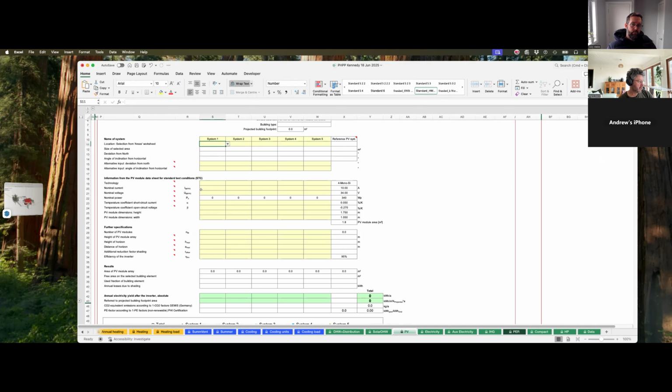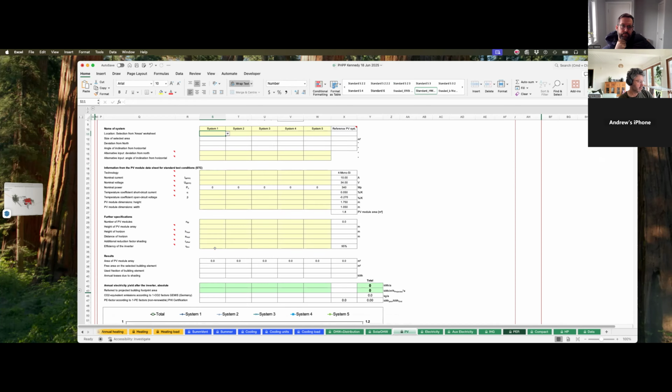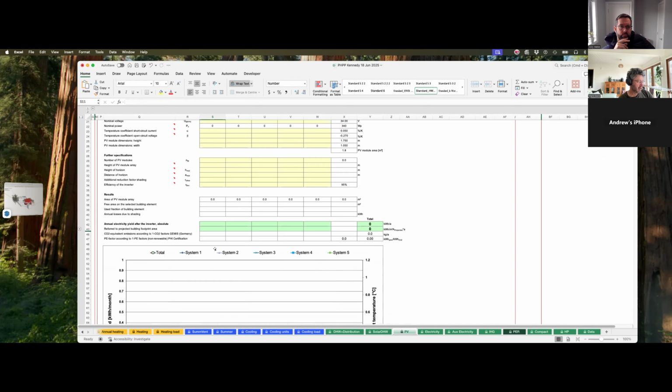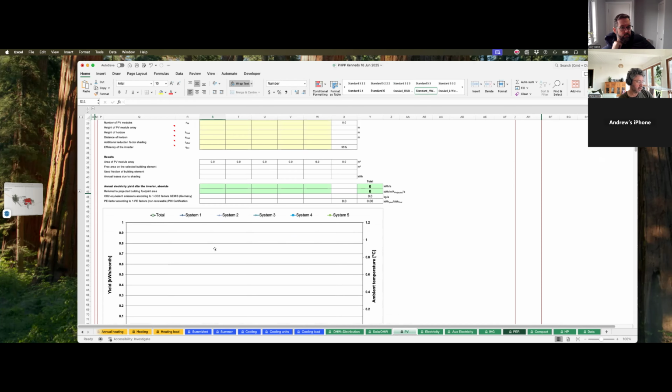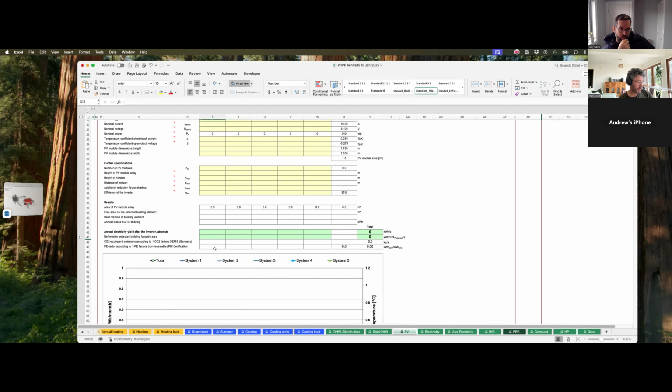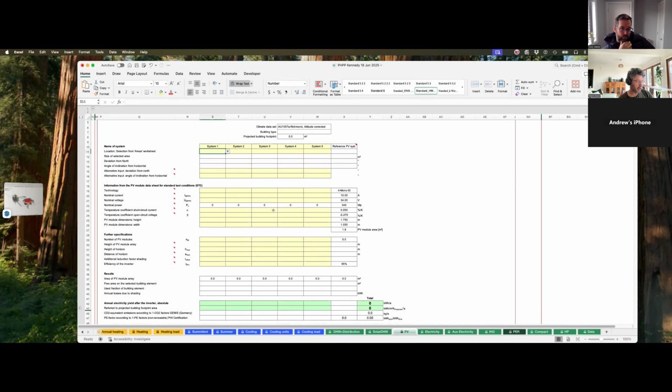The information about the cells, the information about the inverter, etc. And then it'll work out what it figures you'll actually generate. So we don't just put in a 10 kilowatt system and assume we're generating 10 kilowatts. It's varied based on reality.